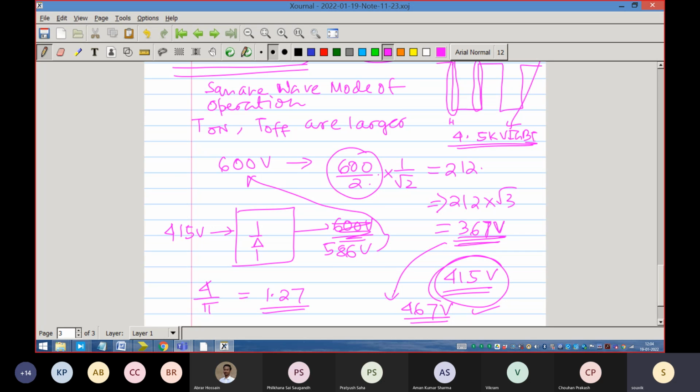That may be less expensive than designing a very expensive inverter, and a technical challenge is there to design such an inverter, because you are not getting an appropriate switching device. An appropriate switching device is not there at that high voltage. A 4.5 kV switching device is not there which has good switching time. One device becomes good or bad as a switching device based on the transitions. How much transition it encounters, how much loss it encounters during transition from on to off or off to on. So these 4.5 kV IGBTs, which are required for such a high voltage system, are not good.